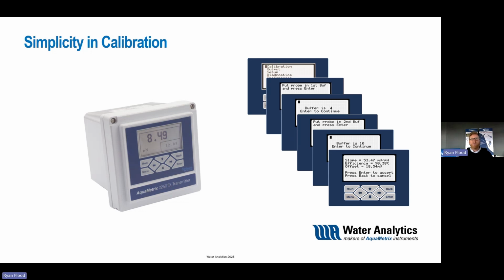I know I've been to some facilities where someone has to write something down, bring it to a computer, transcribe that into different numbers, and then punch those numbers into a PLC to perform that calibration. You lose a lot of time and you open yourself up to a lot of error in instances like that. Also, I've had some instances where people use walkie-talkies to say, "All right, I put in this, I got this reading, punch it into that one."